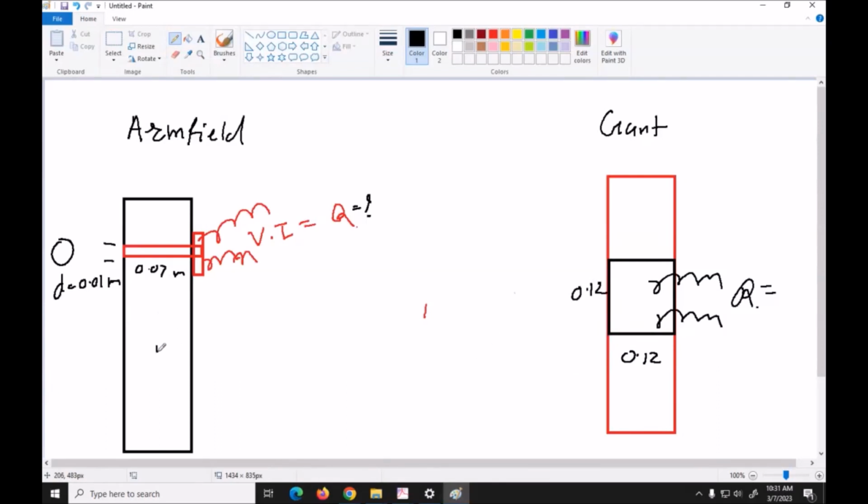Here there is a thermocouple used to measure TA, and here there is a thermocouple that gives you TH. Same here, we need to press the sensor here and we can measure the temperature TH, and there is another thermocouple TA. There is also another temperature here, but we are not interested in that temperature, so we can measure TA and TH here. So our observation is to measure voltage, current, temperature TH and temperature TA.